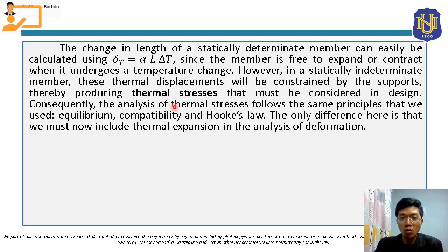If we are going to consider thermal stresses in the computation, we are just going to follow the same principle. We are going to establish the equilibrium equation, the compatibility equation, and we are going to use Hooke's law. So the only difference here is that we must now include thermal expansion in the analysis of deformation. So we are going to include this thermal expansion.